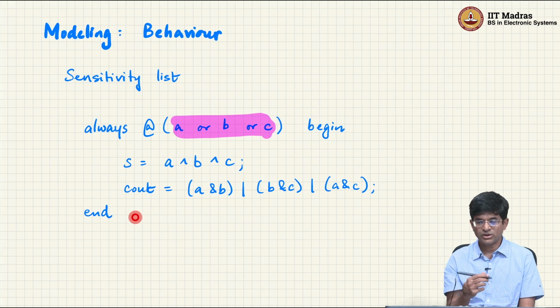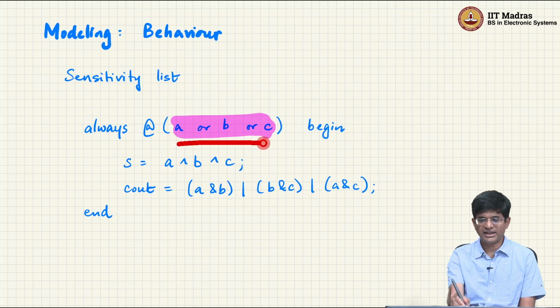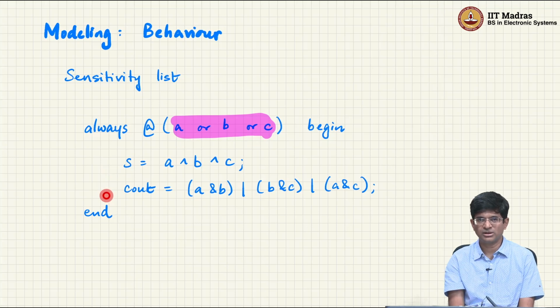Right? So this behavioral modeling can be used in order to model really complex behavior, because now you can have fairly large sensitivity lists, you can have fairly large amounts of logic being expressed inside an always block, and that logic can be complex. It can basically involve multiple conditional statements. It can look at the values of, it can create temporary computations and then use those in order to decide whether or not some other thing needs to happen.